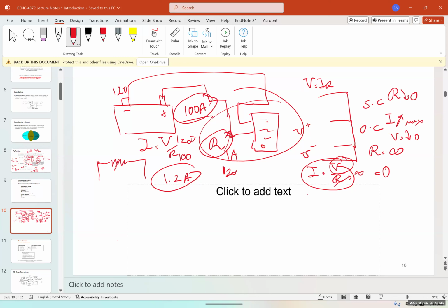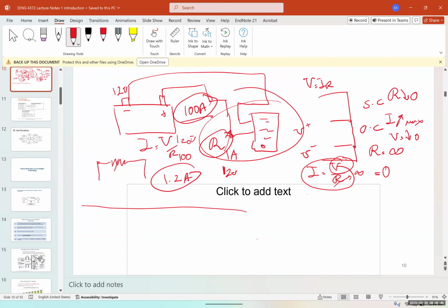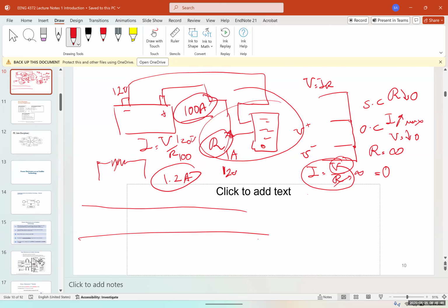And the same thing that I mentioned with outlets. The reason that we don't have any current passing is because it's air. Air has an infinite resistance, you don't have any current. So do we normally see that load in the charger itself or in the phone when it comes to this specific case? If you put a current meter on, that's a great question. Current meter on the line, one of these clamp meters, you could see that only the current is passing. So actually the load is determining. And it's the same with the outlet.